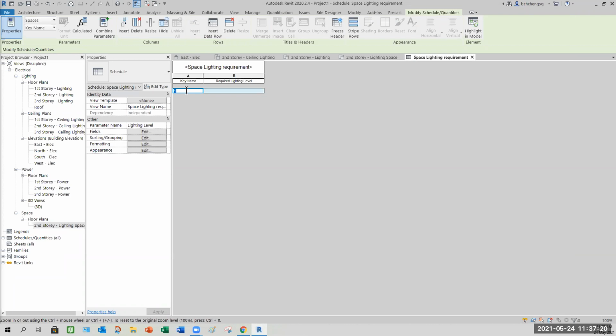You just need to do it once. So here, I will type this as my library. Now library, the lux is 540. Just type 540. No need to type lx because it automatically inserts. Now see this? It's done.